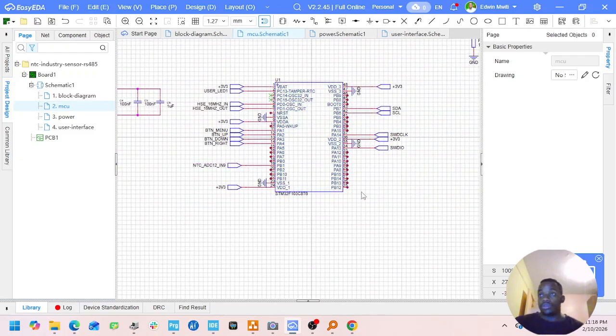The other thing that we should do, at least for a development device, okay, what happens is when you're manufacturing such a device, the program is preloaded into the MCU. Then the programmed MCU is loaded onto the PCB, right? So that's why you see most devices don't have an exposed programming interface like we are doing with this one.